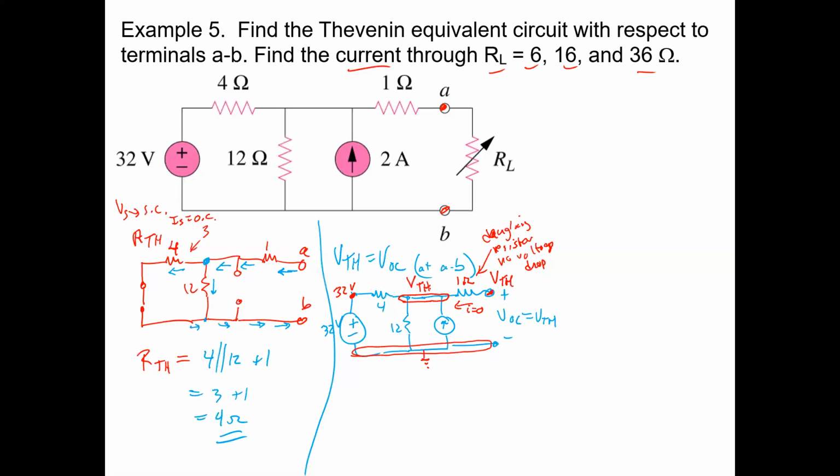And this is one of those little insights you have to have when you look at a circuit to keep the calculations from getting too complicated. If you call that something else, maybe you'll eventually realize when you do KVL or nodal analysis that it's the same, but you might not. You might actually write this: if you call that V1, you would say this current isn't 0, it's V7 minus V1 over 1 ohm. That could lead you astray, because it's the same thing, V7 and V7, so the current is 0.